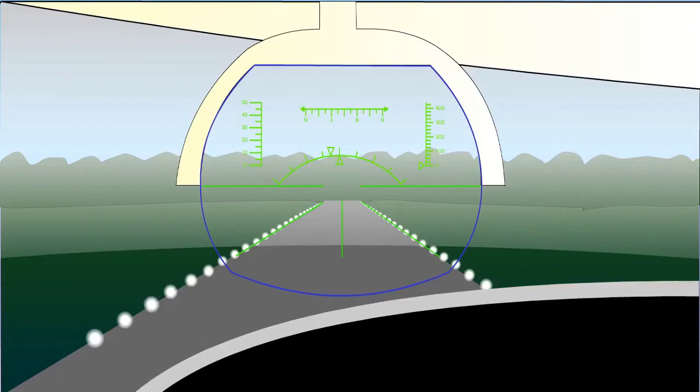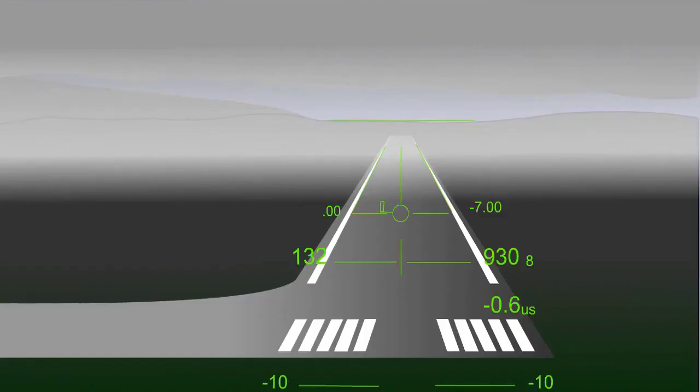It is particularly useful during takeoff in low visibility conditions when only a few hundred feet of runway may be visible, but the pilot still wishes to see it, at least until airborne, before transferring to instruments. Similarly, on landing, especially on Category 3 ILS approaches, it enhances safety by allowing immediate reorientation to external information as soon as the runway becomes visible.